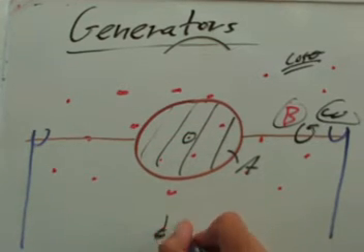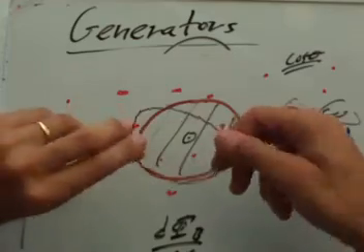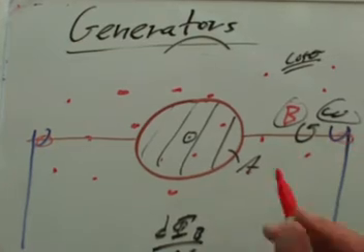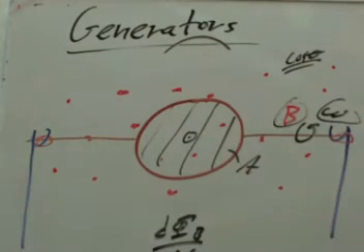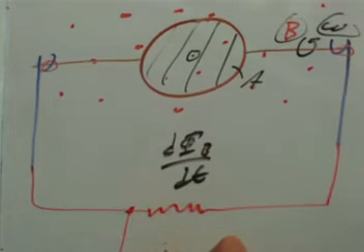But what I'm most concerned about for my voltage is how that flux is changing, the d phi B dt. And that's exactly what you look at by looking at the equation you wrote on the previous screen. But this, in a nutshell, is how an AC generator works. You just take a coil like this and get it to rotate in a magnetic field like that. And if you were able to monitor the voltage, say these things are all made out of metal, and where these things are contacting right here, the currents produced can come out, and you can get a measure of voltage right here. And suppose you ran it through a resistor down here like this, or something that consumed a little bit of that power, and then across the resistor you put your voltmeter here.